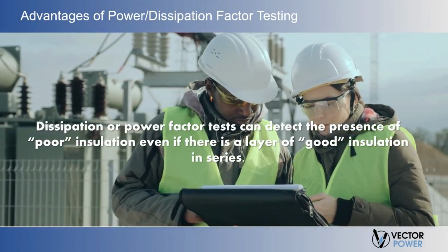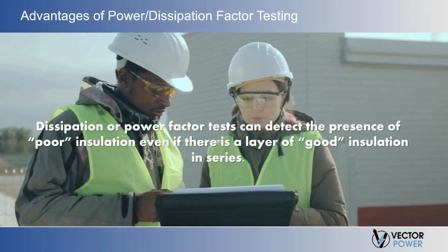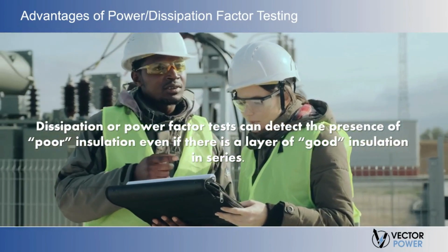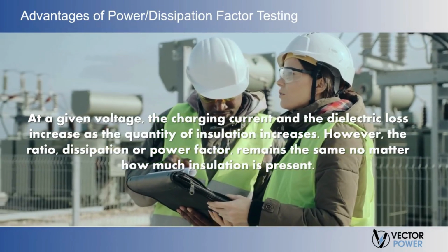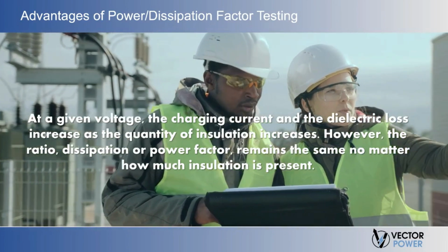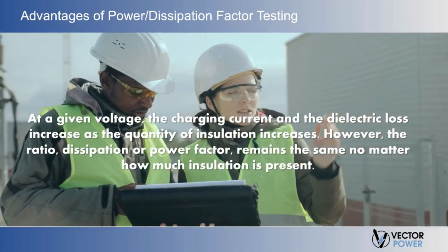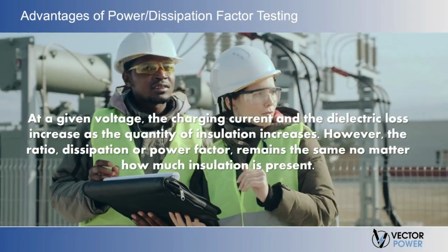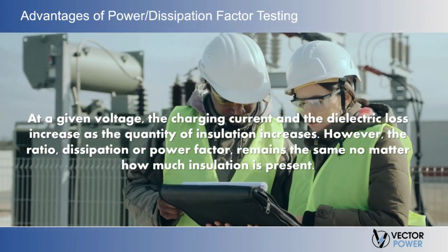Dissipation or power factor tests can detect the presence of poor insulation even if there is a layer of good insulation in series. DC tests usually show a high insulation resistance under these conditions. At a given voltage, the charging current and the dielectric loss increase as the quantity of insulation increases. However, the ratio, dissipation or power factor, remains the same no matter how much insulation is present. This makes it possible to establish simplified test values for various types of insulation.